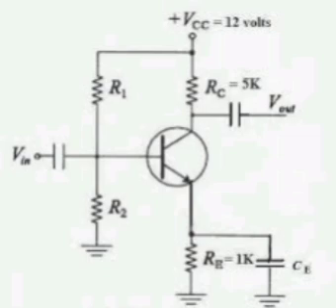The ohm meter shown in the figure uses a 100 ohms basic movement requiring a full scale current of 1 milliamp. The internal battery voltage is 3 volts. The desired scale marking for half scale deflection is 2000 ohms. Calculate the value of R1 and R2 and the maximum value of R2 to compensate for a 10% drop in the battery voltage.